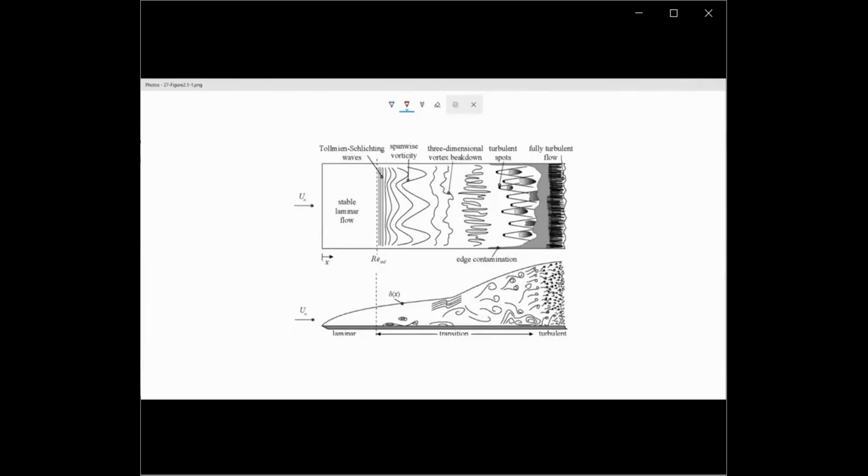Using the integral boundary layer method in the zero pressure gradient case, you obtain an approximate solution, but a quite reasonable approximation of the Blasius flat plate boundary layer case. I think last week Mustafa Hoca finished the integral boundary layer method. That was the last thing.